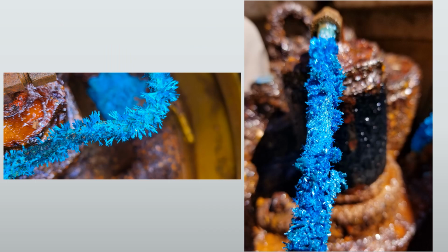A slightly different style of copper corrosion: we get copper crystals that pop out of our mechanical line leak detectors. We get these nice buildups. There is a temptation to knock these crystals off, but this is a passive film that is developed over the copper. So the minute we knock these copper crystals off, we restart the corrosion cell. So this is the copper trying to protect itself. Again, just great pictures, great crystal structure.